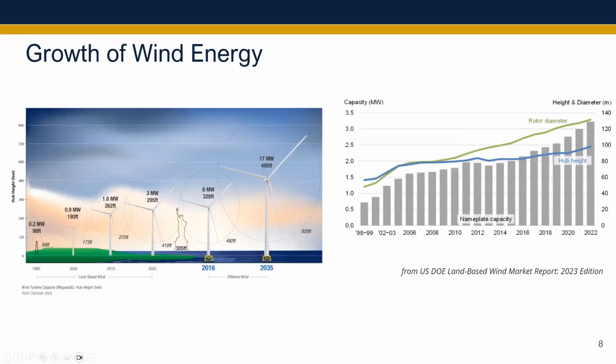That's in terms of the share of wind, but in terms of wind generation and how the technology developed over the years, back in the 1990s we were talking about 0.2 megawatt with towers in the order of 80-some feet, then 173 feet. Now in the onshore, we have about 150-meter wind turbines, and we are at about 6 megawatts of production with the technology.